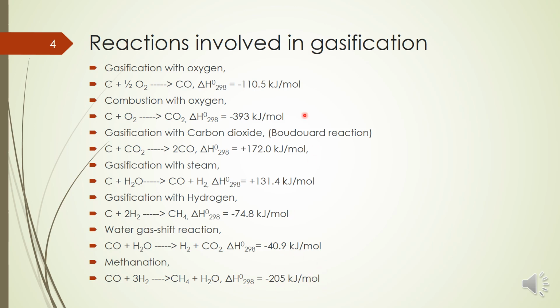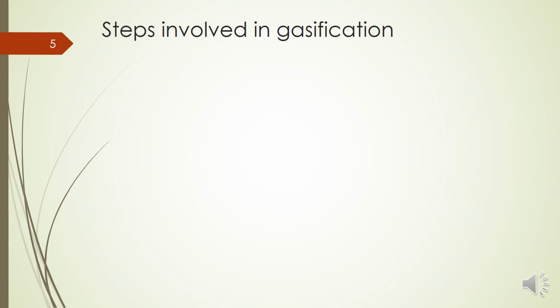So you can see most of the reactions are exothermic, so heat is liberated. A few are endothermic, so that heat can be utilized by these reactions. So these are the important reactions to be considered while studying gasification. Now gasification can be split into mainly 4 steps, that is drying, pyrolysis, reduction and oxidation. In any gasifier, these steps will be taking place in different locations and at different times. Try to understand what these processes are.